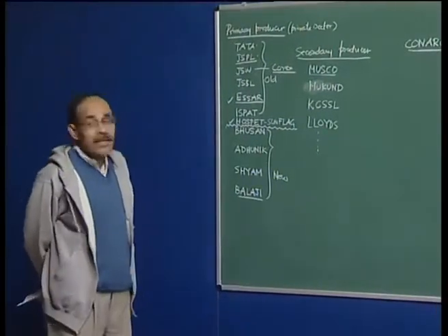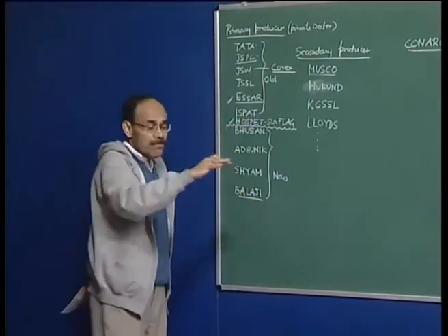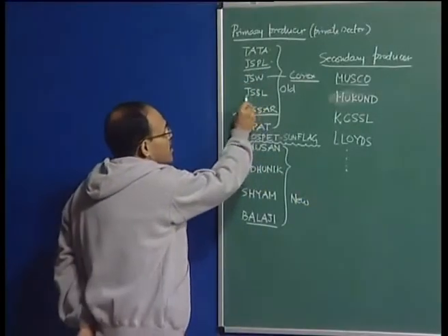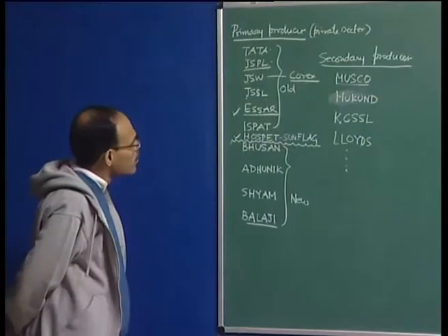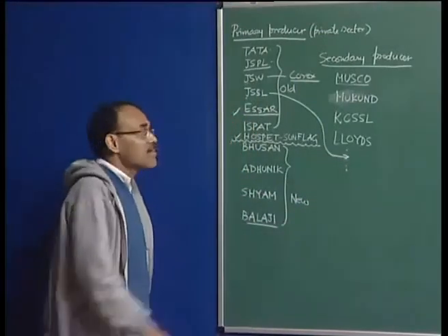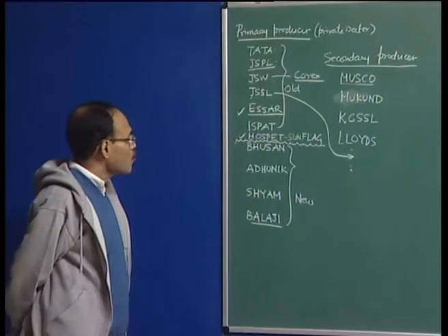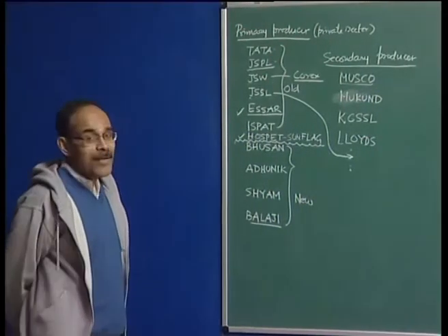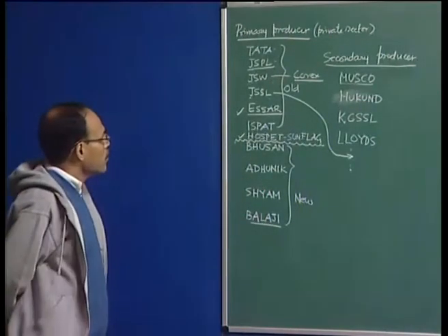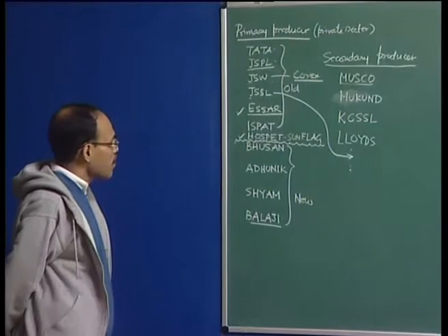They produce slabs. There again the hot metal is produced through Corex as well as blast furnace, and then we have steel making, which is done through LD steel making. Jindal Stainless is an old plant, it's not actually an integrated steel plant, so I should not have put it here. This is an alloy steel plant. They make stainless steel, and they have an electric arc furnace where stainless steel is produced. They also have continuous slab casting facilities. All these plants have, actually, SR Steel, I have already mentioned, electric arc furnace based, slab casters, flat product mill.